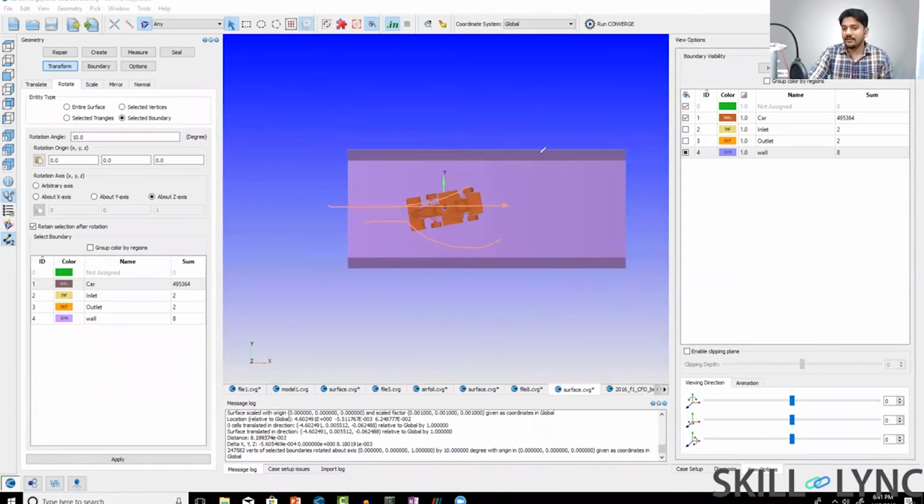And what I'm saying is, depending upon the track, right? You can imagine that there's a track like this, and that is why the car is actually turning like this, correct? So depending upon the track, you should have a good understanding of what the typical yaw angles are. And this is where experience comes in. You take the car, you drive it on the track, do a test drive, and then understand what the turns are, what the turn angles are. And you understand that for 95% of the time, or 90 or 70% of the time, the turning takes place, maybe that's a 10-degree turn. Then you need to make sure that you test it accordingly.